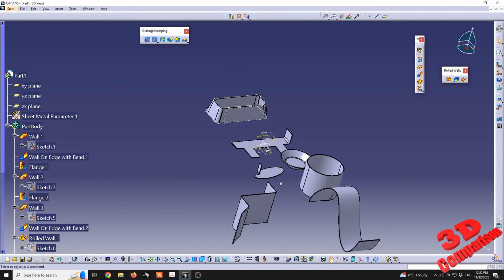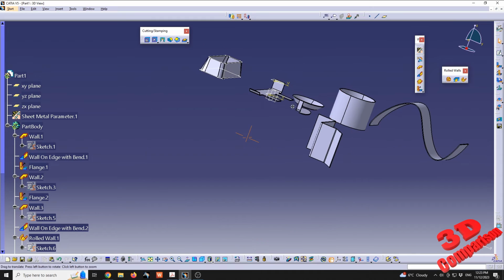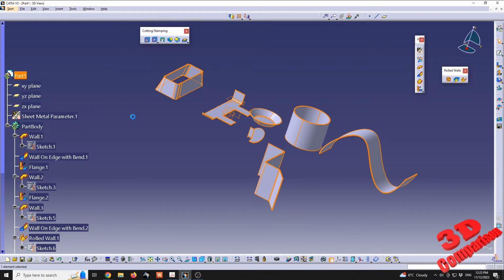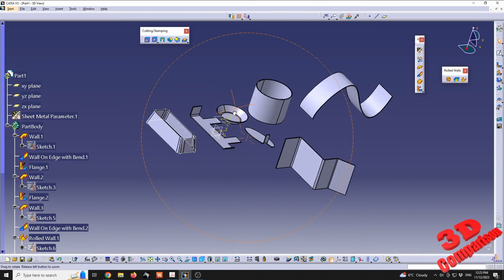And we have that hopper profile, which we can further go and have this folded and unfolded. So keep in mind that within generative sheet metal design, it's usually a good practice to use multi-bodies, and I will create another video regarding that, how we can merge additional part bodies within the same part and have those converted into only one sheet metal part.